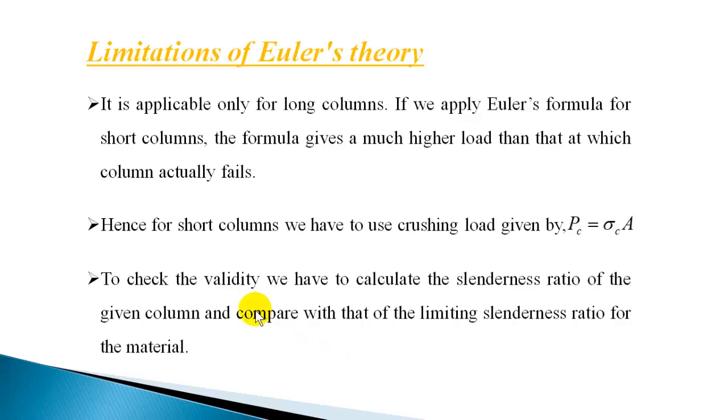When it's a short column, you cannot apply Euler's formula, and it gives a larger load than the column can actually support.